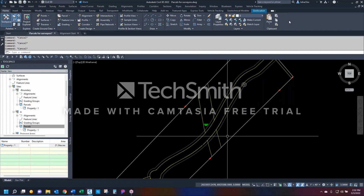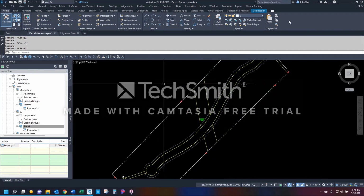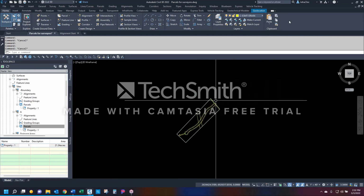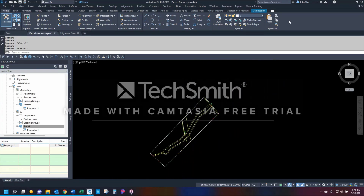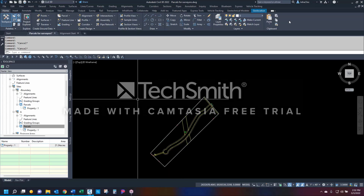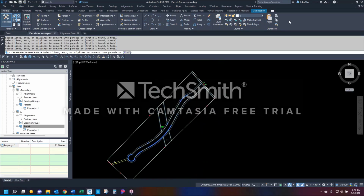Okay, so we did a parcel by object. We're going to do another parcel by object for this guy, and these guys because they shouldn't be part of it, and these two, and that bugger. So all these yellow lines are going to become a parcel by object, and we're going to do them all at one time, and then we will change up what they look like. Parcel pull down on the Home tab of the ribbon, Create Design panel, parcel pull down, Create Parcel from Objects. Select all the yellow lines one at a time.